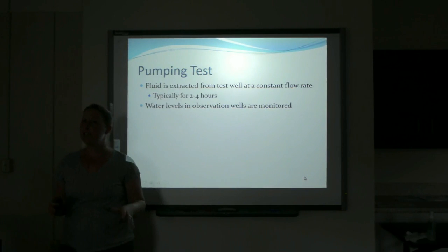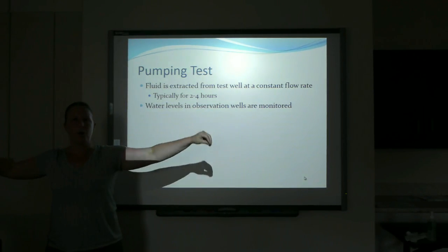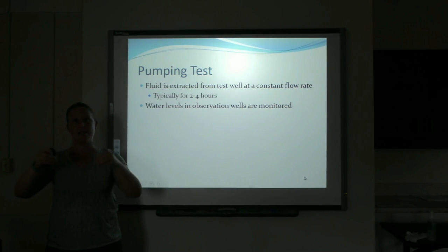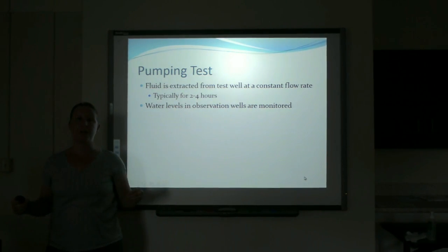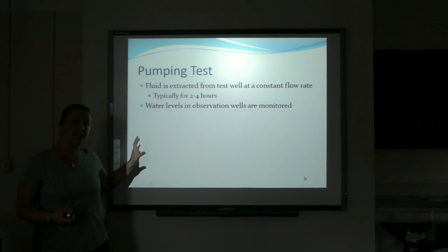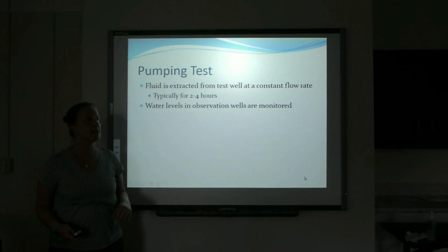With a pumping test, you're doing something similar, but you're using multiple wells. You'll have your pumping well, and you'll pump water at a constant rate, usually for about 2 to 4 hours out of that well. And you'll monitor the water level changes at multiple observation wells at known distances away. From that, you can calculate the hydraulic conductivity of the aquifer. In general, pumping tests are going to be more expensive but more accurate than slug tests or packer tests.